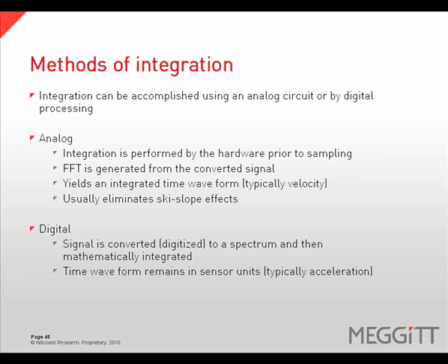With a digital process, the signal is digitized and then converted or integrated mathematically. The FFT is then created from the converted signal. The time waveform will remain in the sensor units. This is why digital integration is often used.